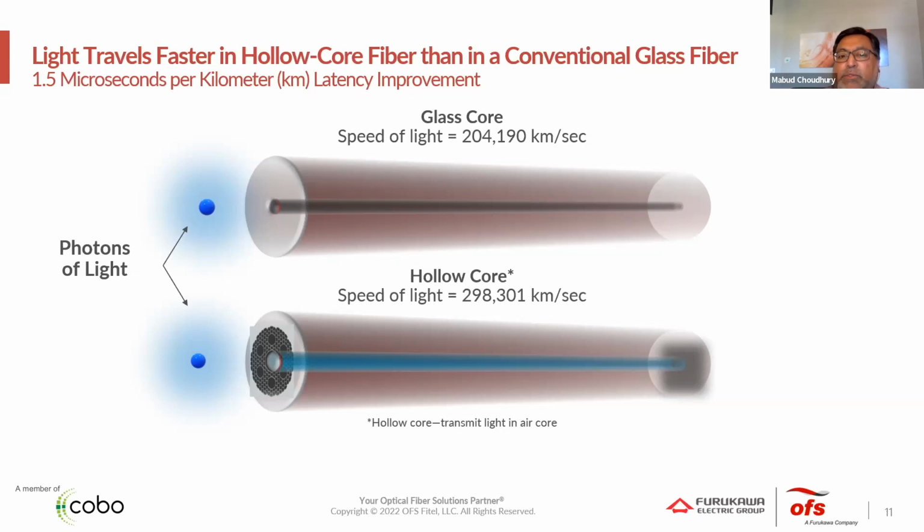The technology that's used for the OFS hollow core fiber is photonic bandgap technology that allows you to, again, transmit through air. So the silica or the glass forms a structure that allows that air guide to carry forward without having issues with PMD, with MPI, with chromatic dispersion. It's naturally a few mode fiber, and so you have to take care of the higher mode orders, attenuate that, and that's a lot of the engineering that's gone on with this fiber. The concept is about 20 years old, actually. There's almost 10 years of R&D behind it.